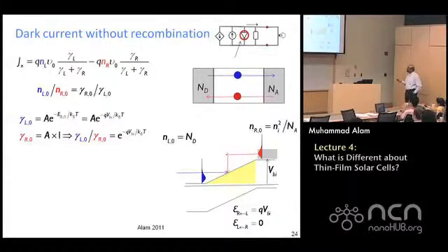And if you do that, you remember the probability of going from the left to the right is exponentially suppressed, because there is a big barrier here, right? Big barrier, p-n junction barrier, and so that is exponentially suppressed. And correspondingly, this one, on the other hand, if somebody is trying to come from here and go to this side, of course there's no barrier, so that's 1. And you can just insert this in this formula.